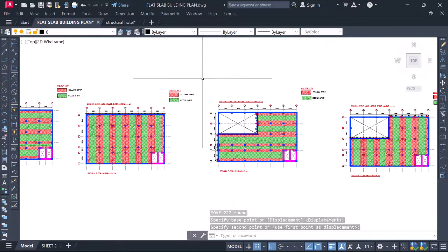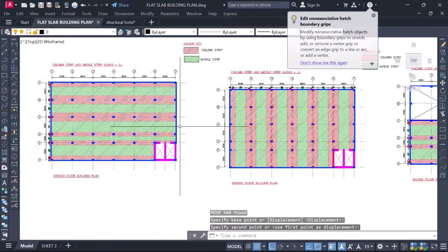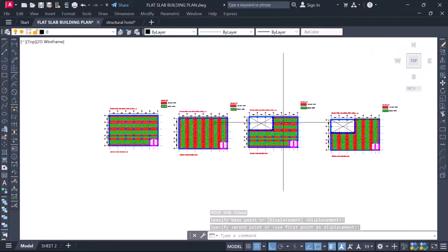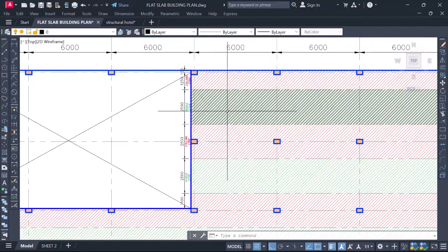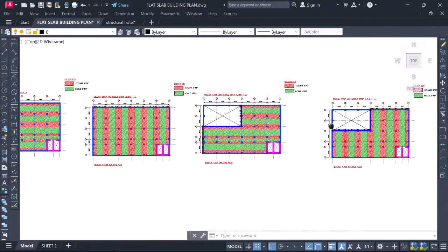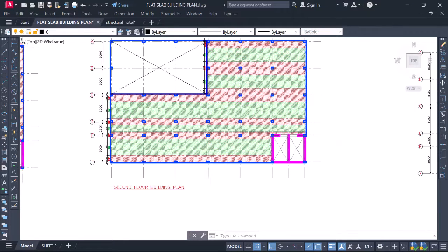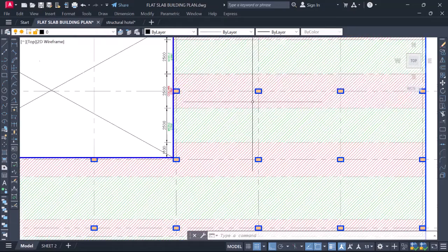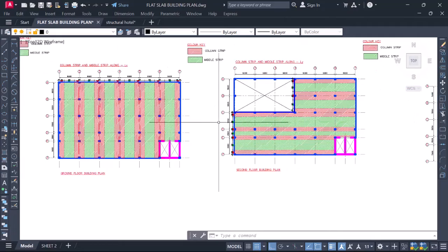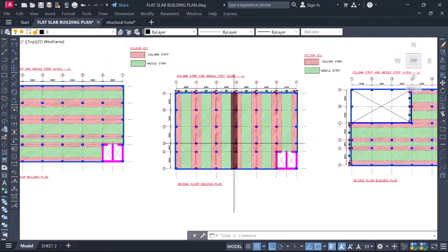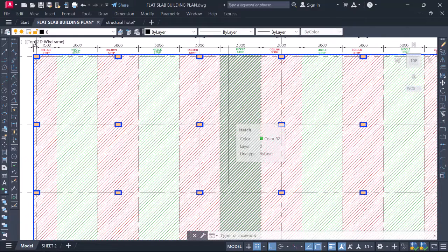Okay, so right now you can see what we have just done so far. You can now see how we have done the GA of the flat slab by calculating our column strip and our middle strip. So without doing this, don't venture into performing flat slab design at all in any software, because you must understand this. You must have done it manually first by calculating your column strip and middle strip, else you will have punching. Now in one way, I would say that we have controlled at least 25% of punching failure that would have occurred on this flat slab.